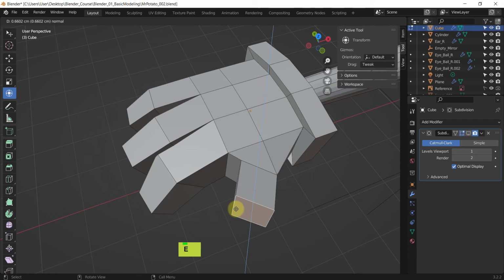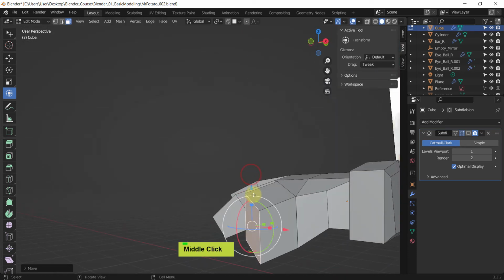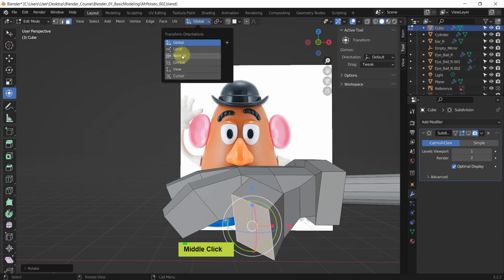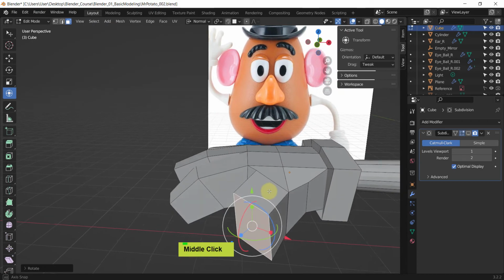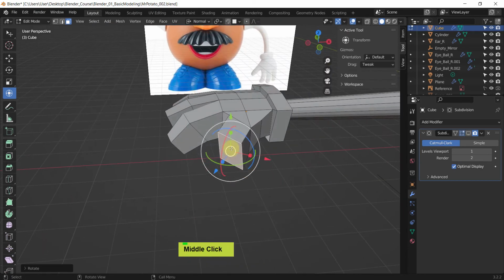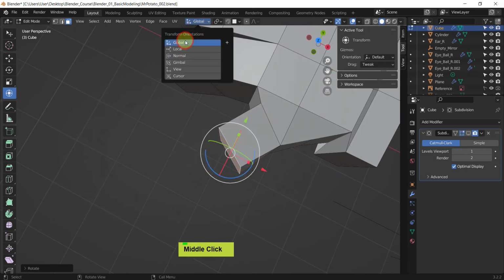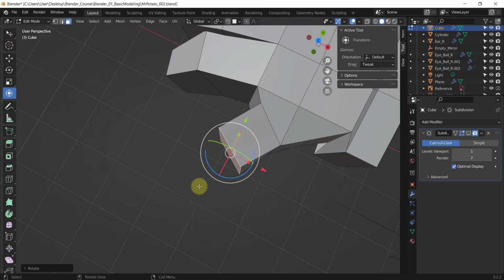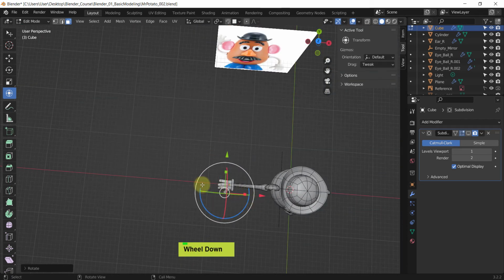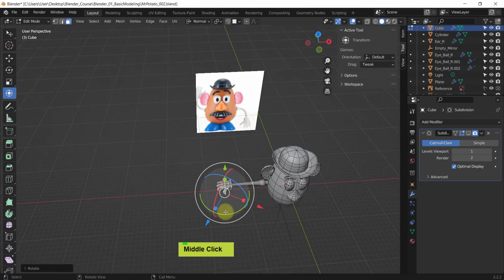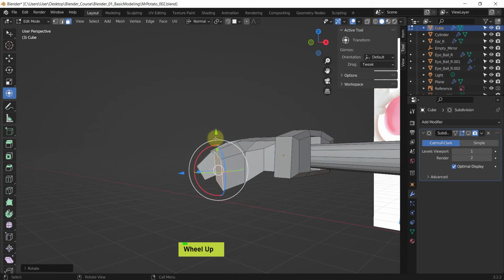So, face extrude. And before I move on, I like to check what's going on. I'm not sure, but probably we can switch to normal. Yeah, so normal can help us to orient the 3D gizmo according to the position of the face in the 3D space. By default, this is global, measuring the overall scene, so it's aligned to the scene. You can see everything is aligned according to that. So the green one is pointing that way, the red arrow is pointing that way. But in real life, this whole thing is positioned somewhat like this, canted and slanted in the 3D space.